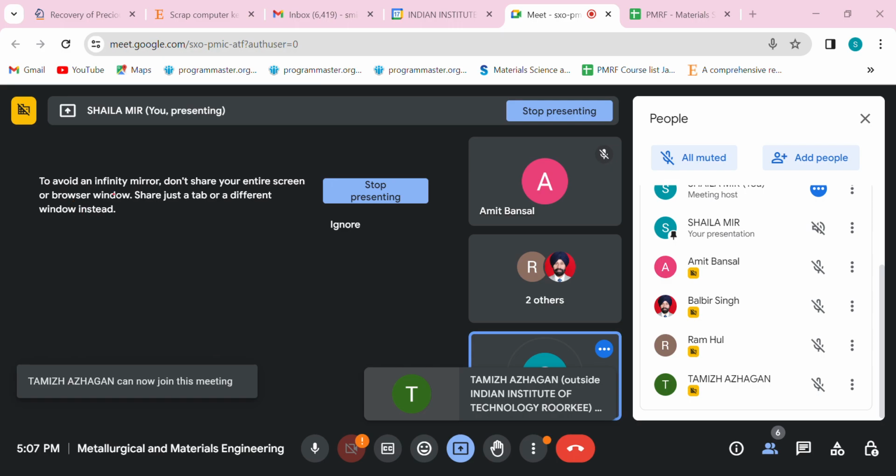So for Rockwell, we have two types of indenters, based on which scale you are operating. You have a Brale indenter, which is the cone-type indenter, and you also have one type of indenter based on steel balls. And then you have Brinell. Brinell has the characteristic form of steel balls, and I think they are 10 mm sized steel balls, if I'm not wrong, which are used for the indentation.